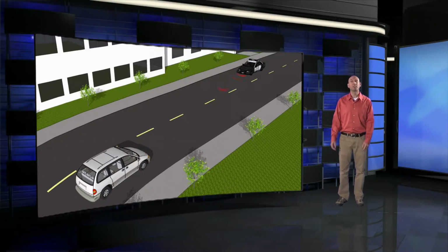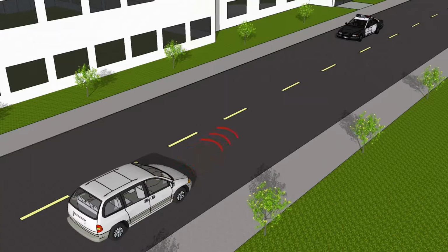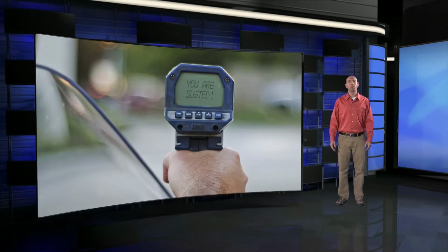The first one I'd like to talk about is Doppler radar. Doppler radar, most of us are familiar with it because of its use in speed guns in law enforcement. So it operates on the principle of transmitting an electromagnetic wave that then bounces off of a target. If it's a moving target, then this electromagnetic wave will experience a shift in frequency, known as the Doppler shift. So the received signal then will be at a slightly different frequency than the transmitted signal. The Doppler radar device will compare these two frequencies, and the difference between them then will be proportional to the speed of the target. This makes it a good technology for measuring speed for law enforcement.